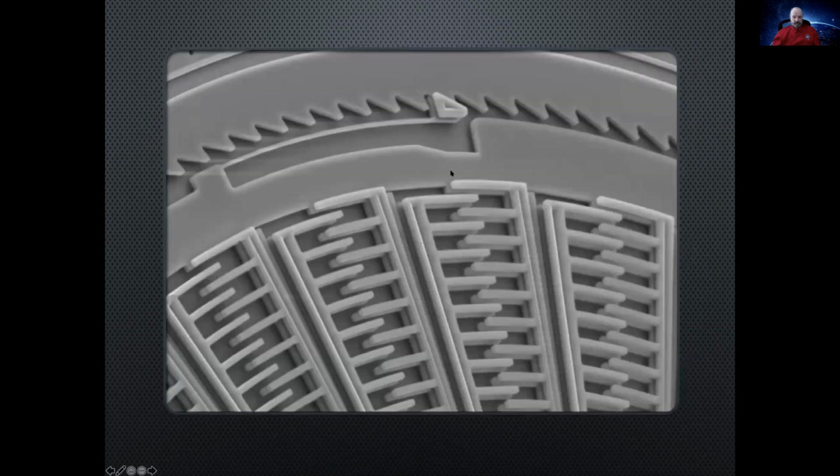Okay, so let's take a look at a close-up. So here's a drive pawl. So when these two sets of teeth come together, that means one thing is rotating relative to the other. So this frame, this interior frame, is going to move counterclockwise or to the left. This is going to move to the left and drive this ratcheting ring one tooth over. And then this will snap back and this will jump over to the next tooth.